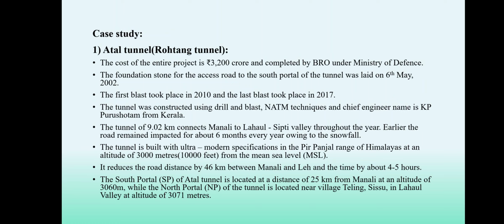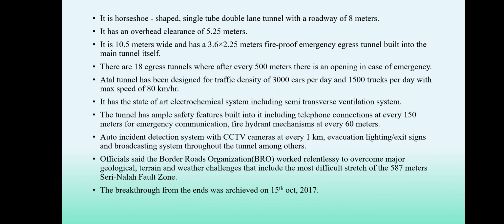Earlier, the road remained closed for about 6 months every year owing to the snowfall. It reduced the road distance by 46 km between Manali and Leh, and the time is reduced by 4 to 5 hours. It is a horseshoe-shaped single tube, double lane tunnel with a roadway of 8 meters. It has an overhead clearance of 5.25 meters.